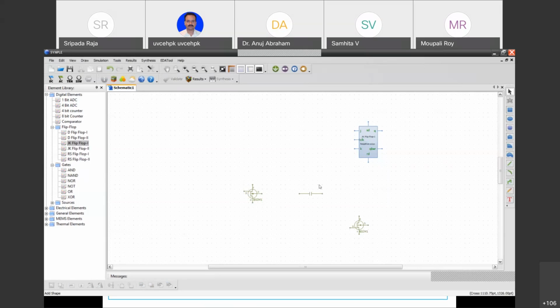Readout integrated circuits are important, and you can interface them here within the software itself. Then for further gate level simulation, or to interface this with nano circuits, you can do it on the Synopsys or Cadence tool. You can push this to a VHDL file.